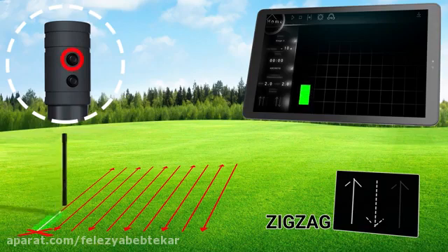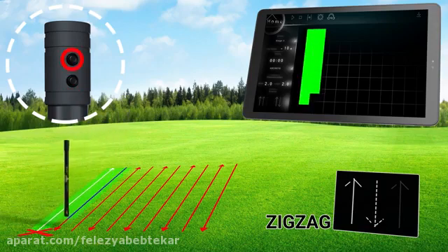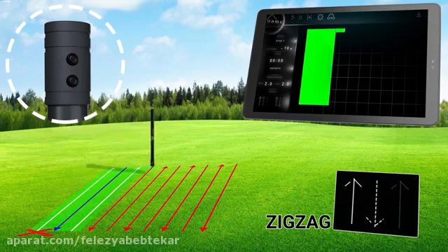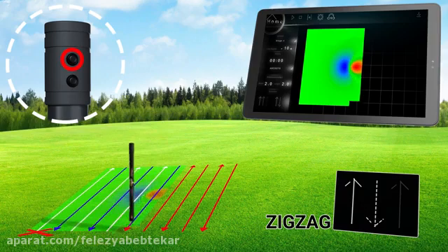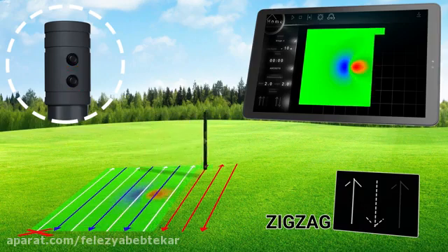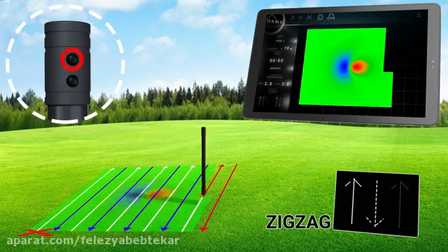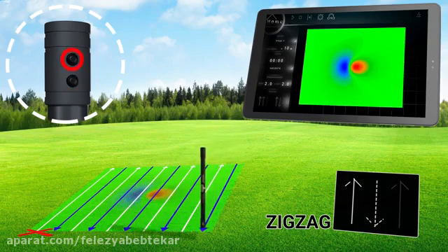As you can see in the video, data recording and ground condition can be seen accurately in the software. Reaching the end of each line, we go to the beginning of the next line by pressing the new line button and hold down the data recording button again. In each image, the 2 scanning forms are fully visible, parallel and zigzag.